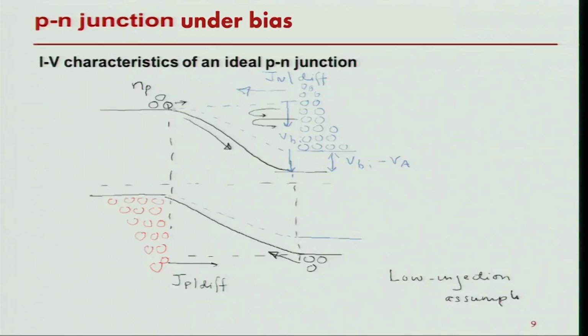This is to say that there is injection of the electrons from n to p side, but the amount is so small that it is only changing the minority carrier concentration and it is not changing the thermal equilibrium concentration of the majority carrier by any significant amount. So, if I have a forward bias, I would have a diffusion current because of this extra injection into the bulk region of the PN diode, and the drift current does not change too much.